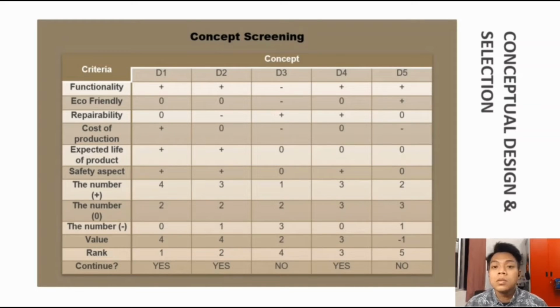This is the decision matrix that is used to choose which concept will be studied further. The symbols can be used to symbolize 5 different relative performances as illustrated in the table. By counting the number of plus or minus, each design received the total finding. Finally, the total number of minus was subtracted from the total number of plus to arrive at the final result for each design. After that, from the table, we see that 2 design ideas were rejected and 3 were chosen.